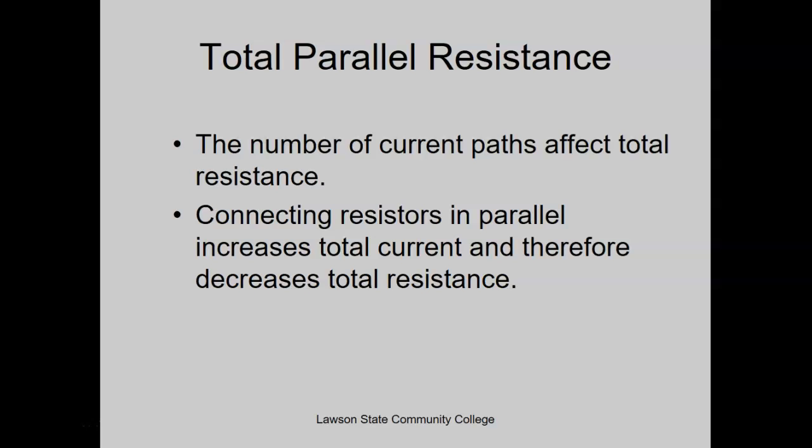Any of you? Or does everybody know better by now because they know that increasing that total current is going to increase the likelihood of what? The more loads you add, in other words, the more things you plug into that circuit, the more likelihood you are of tripping your breaker, hopefully, tripping a fuse if you still have those in your house.